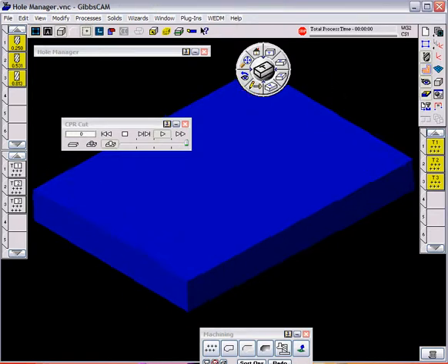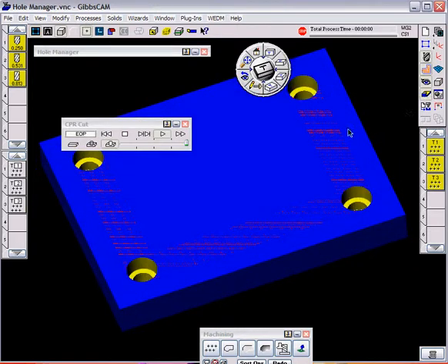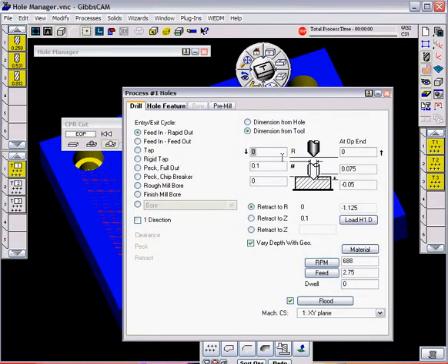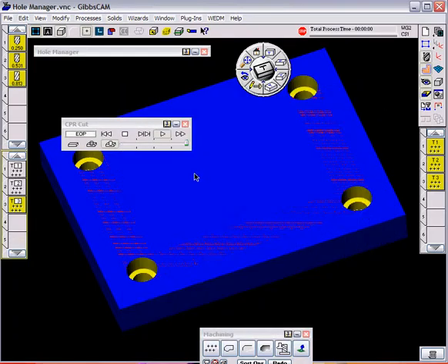And other than that, we're good to go. Notice we're dragging a tool across here. So let's go ahead and put some height on these clearances. Going to enter and exit 100 thousandths above Z0 for all 3 of these operations. Okay. And we'll go ahead and redo those processes. And now we see that the rendering gets rid of the red.